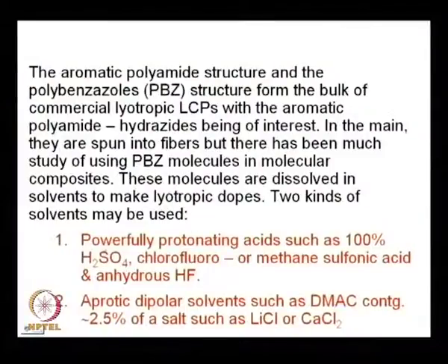Two kinds of solvents may be used. Look at the solvent: concentrated sulfuric acid, or chlorosulfonic or methane sulfonic acid, or anhydrous hydrofluoric acid, hydrogen fluoride. You see, very critical solvents, very strong or harsh solvents. Or aprotic dipolar solvents such as dimethyl acetamide containing 2.5% of a salt to increase the polarity. Actually, these materials, lithium chloride or calcium chloride, increase the polarity of a solvent. Sometimes if a solvent is unable to dissolve a solute, then you add certain electrolytes which will increase the polarity of the solvent, and that will easily dissolve the solute.